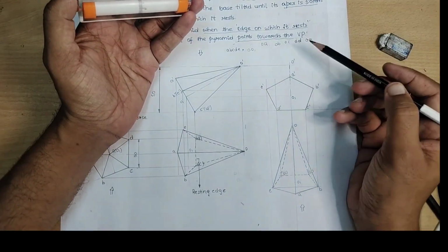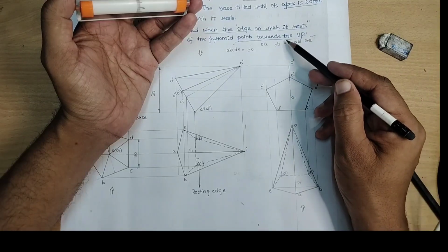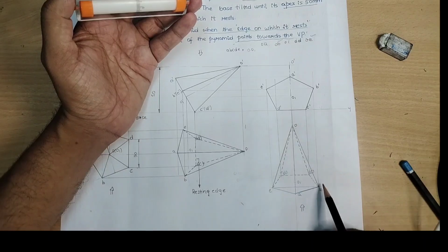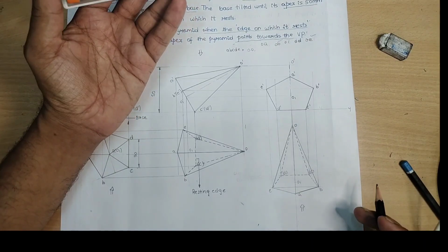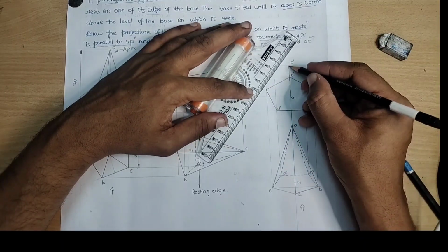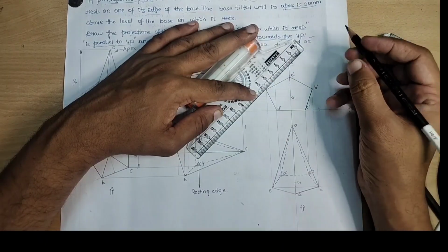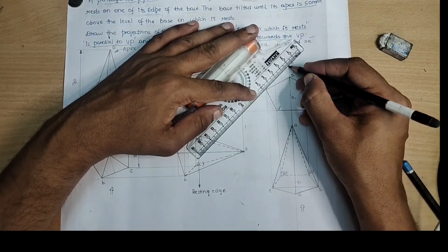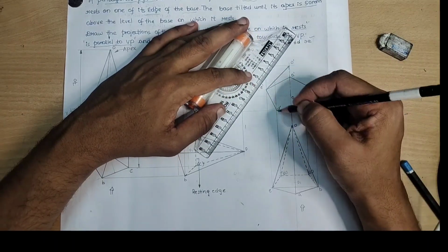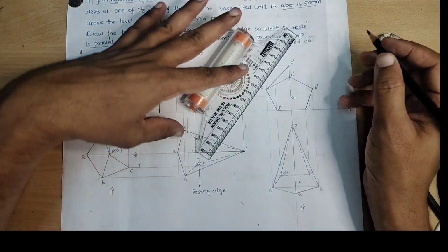This is also over. What is the condition of each line? O to E and O to B. The observer is looking from this end, so the E and B points are close. Please do remember one more concept. This is the outermost boundary. The outermost boundary is always visible even if it would otherwise be invisible. You can make a note towards the side of the paper. In the sixth position, whenever you are drawing a line from O to E, this becomes the outermost boundary. This is the last line you are drawing for that particular side. Hence, it is always visible.